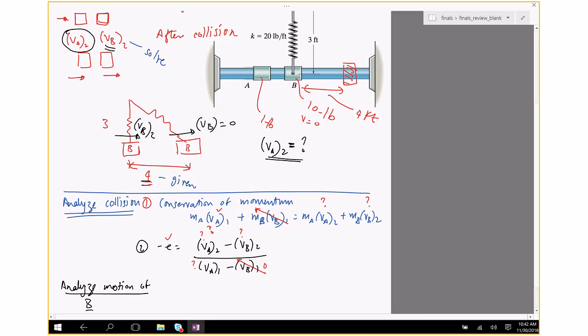So if its velocity is a function of distance, then it is number 2. Number 2 says if there are only conservative forces, use conservation of energy. In this case, the only force is due to the spring, and so we can use conservation of energy. If that rod had friction, then you cannot use conservation. You'll have to use work energy. So no friction. Nothing has been said about friction, but you can make the assumption if nothing is given.